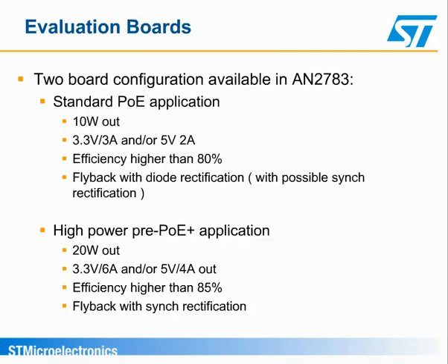Now, let's consider the evaluation boards. Two different power scenarios can be supported by populating the same board with different components. The first board scenario targets standard PoE applications with up to about 10 watts as output, meaning 12.95 watts as input. The second supports up to 20 watts as output, which is twice the value expected with IEEE 802.3AF applications.